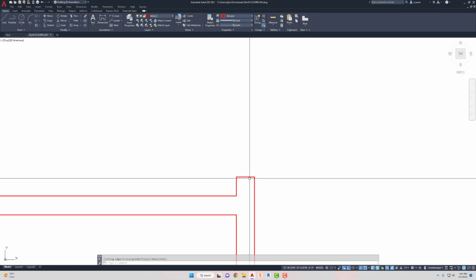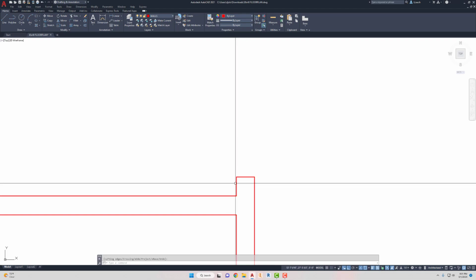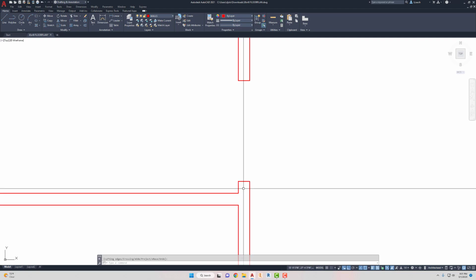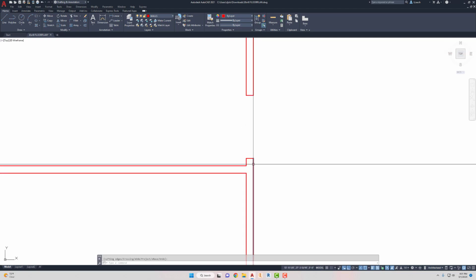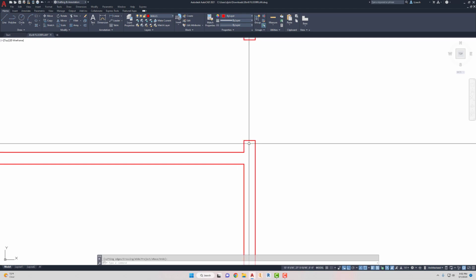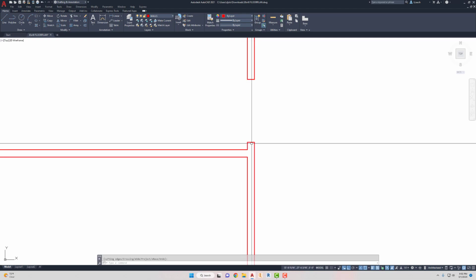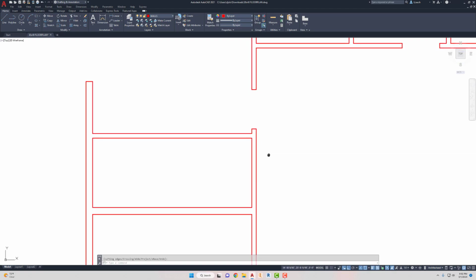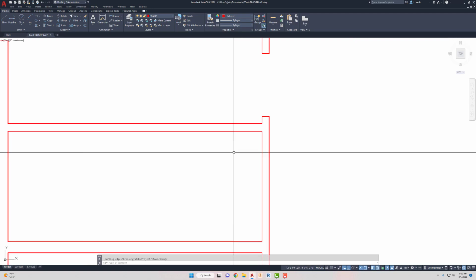And the closest you can have a door, technically, to the wall is 4 inches because you got a double 2x4 kind of framing going around your door there. So as a minimum, try not to make your door any closer than 4 inches to the nearest wall there. Same thing for the restroom here.